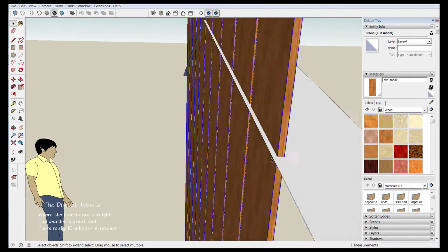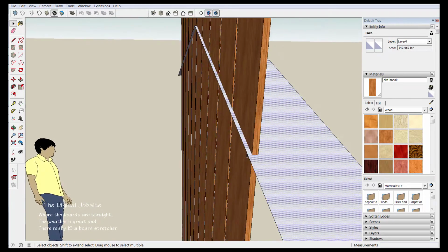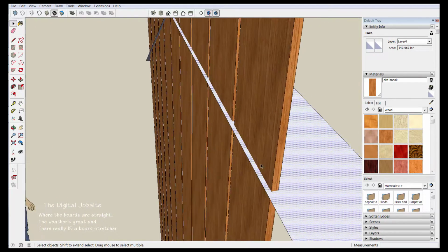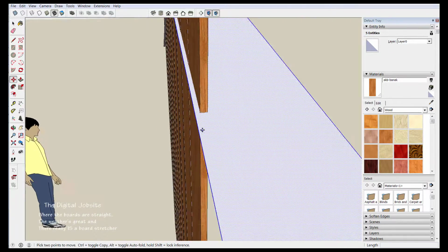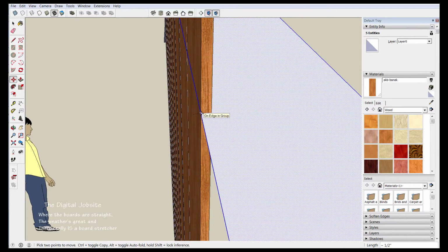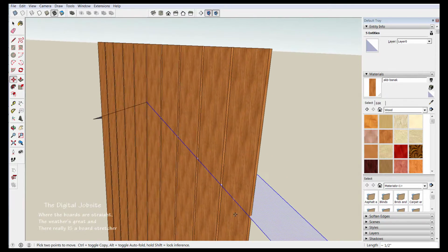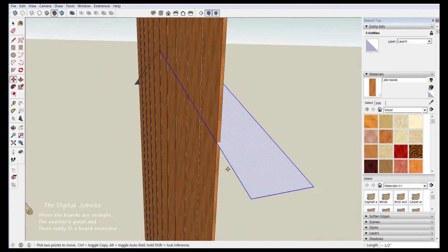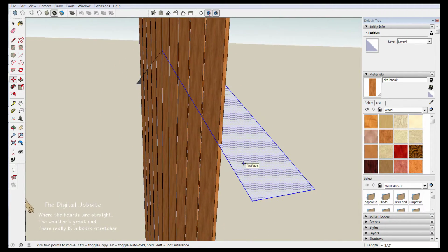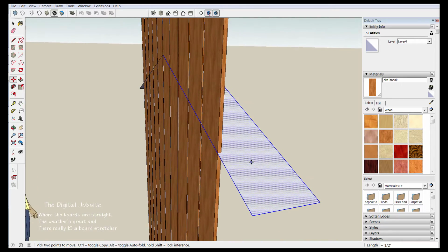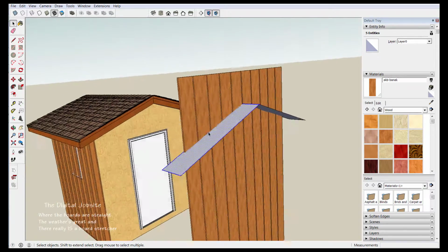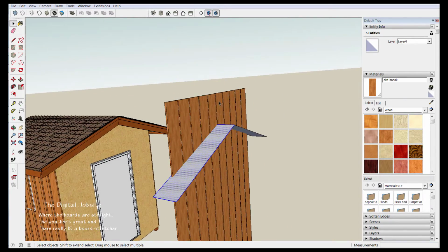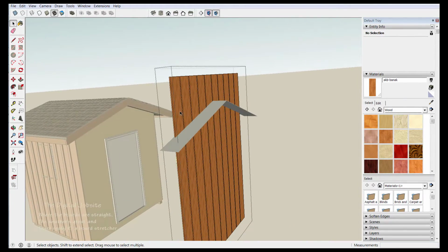And it's important that the bounding edges of this cutting plane are not in line with the surface of the siding. In other words, I don't want this cutting plane to be lined up like this, where the line's actually on the surface of what we're cutting, because that really complicates the cutting process that we're going to do next. So I'm going to use the back arrow key to move that out. All right, so we've got 2 cutting planes for the gable soffit, and then inside this group, we've got groups of groups.